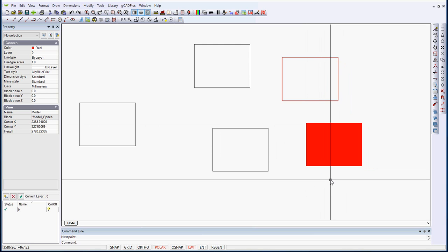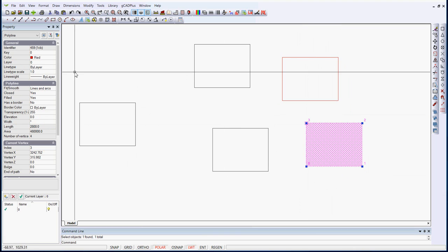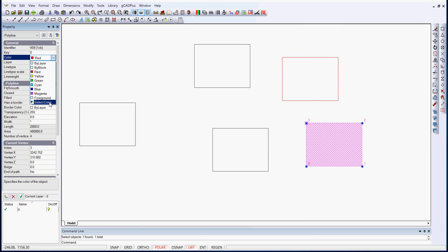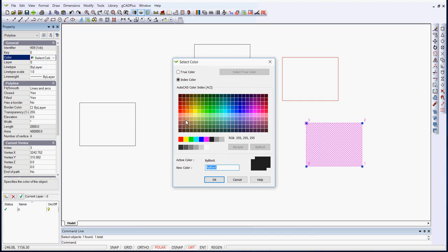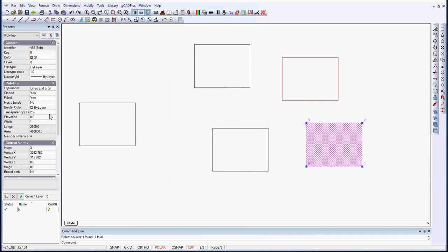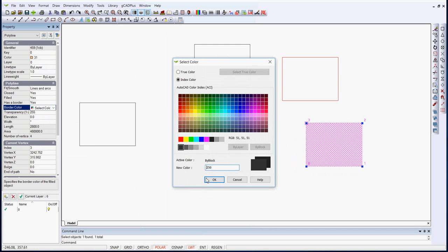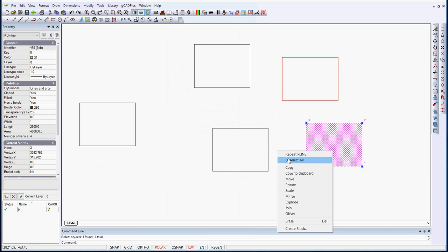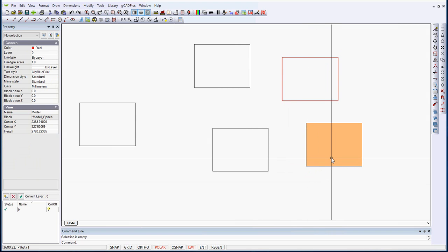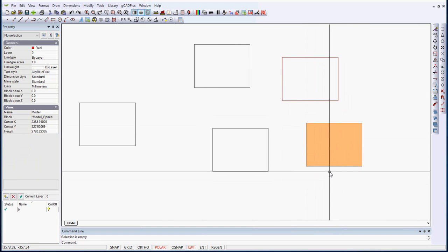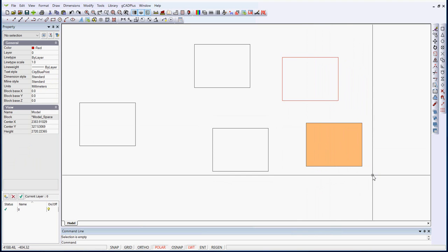We could change its colour quite easily. Let's pick a sandy colour for it, and we'll pick something like this here. And what we will do is come over to the properties box, and we'll say, yeah, this one has a border, and the border colour, we're going to pick dark line and unselect all. Now there's our paving brick with an appropriate colour with a line around it, and it's just one entity. It'll take up very little space in the drawing.